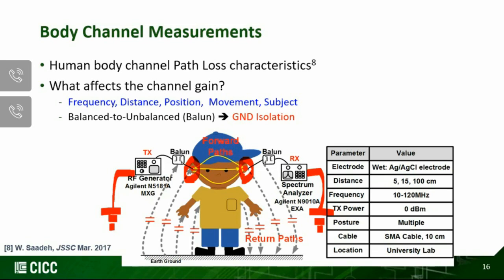Okay, even better is if you can use a mobile or battery-operated TX and battery-operated RX. But also note that if you have a large ground plane in the TX and a large ground plane in the RX, that will also contribute to inaccuracy in the measurement. So having a balloon is a good compromise.